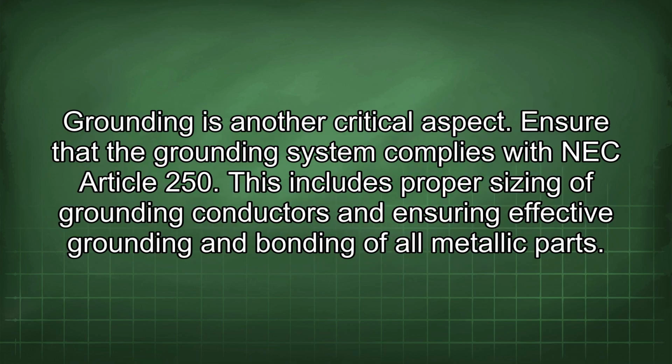Grounding is another critical aspect. Ensure that the grounding system complies with NEC Article 250. This includes proper sizing of grounding conductors and ensuring effective grounding and bonding of all metallic parts.